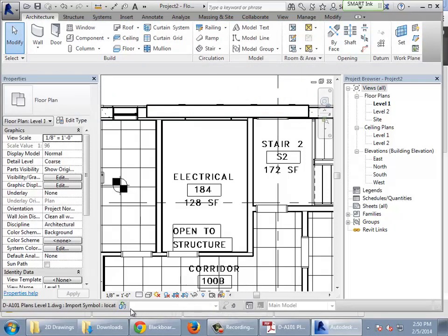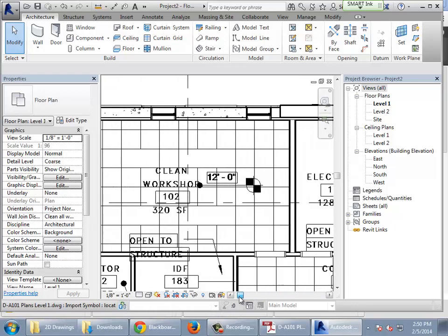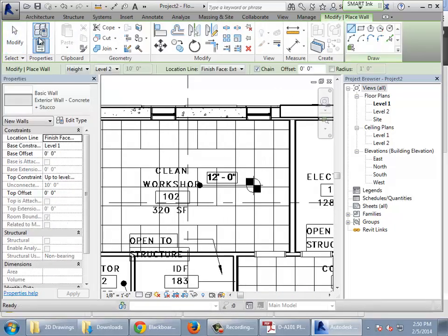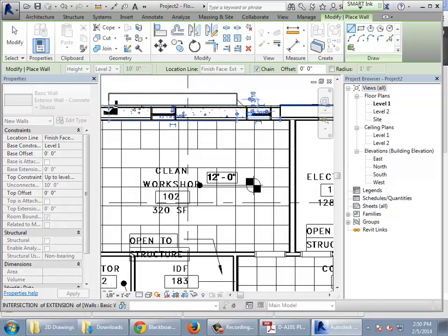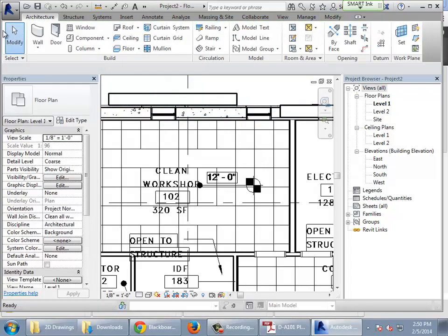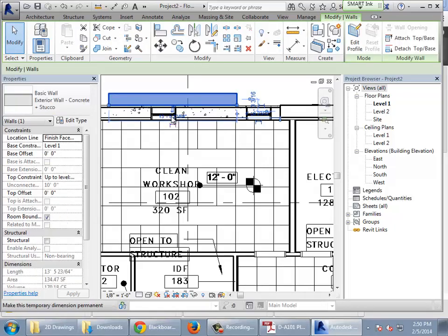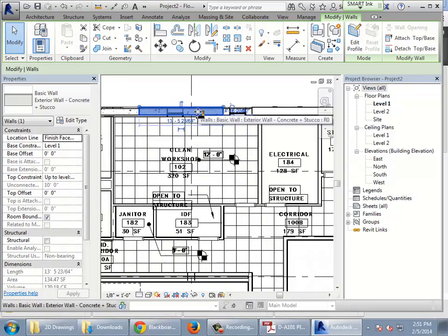If you do it the other way, which is I'll grab that same wall, but I go this way, it'll put it on the other side of the wall. So there is a notion, as it lays down the wall, of which side it puts the thickness on relative to the line you trace. Not to worry, if you do put the wall on the wrong side, you can choose it and click that little glyph, and it'll flip it over and give you the right side of the wall. Okay. So we can do that.